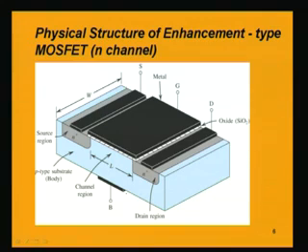So, here in between the two n type semiconductors, which are the source and the drain, we are denoting this length as capital L. Basically this L is denoting the length of the channel. Now, what is the channel that we are going to study? There is another term which is the width of the channel, and it is denoted by W. It means the width of this whole channel.